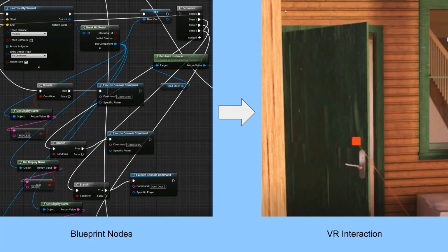I used the blueprint system, which was built in the Unreal Engine, to create certain functions for VR interaction. Since Unreal's blueprint has a significant advantage for visual scripting, I use this node-based blueprint for my VR development. The picture on the left shows how I did the pointers for the controllers and how I used them to execute the animation for opening the doors in the building. These details will be explained later in the demo video as well.